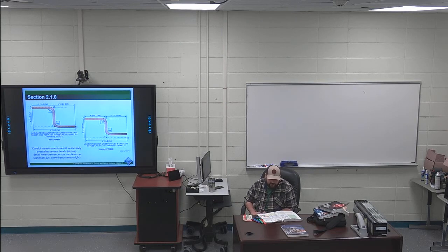Second sentence is highlighted. Use a ferrule or a wraparound designed for assembling compression joints as a guide to make measurement marks all the way around so the mark is always visible. So you're marking all the way around the pipe. Usually you're doing this with a pencil. They show it with a pencil. That way, after you're done bending everything, you take your finger and a little bit of cleaner and wipe your lines off. It looks a little bit more professional.